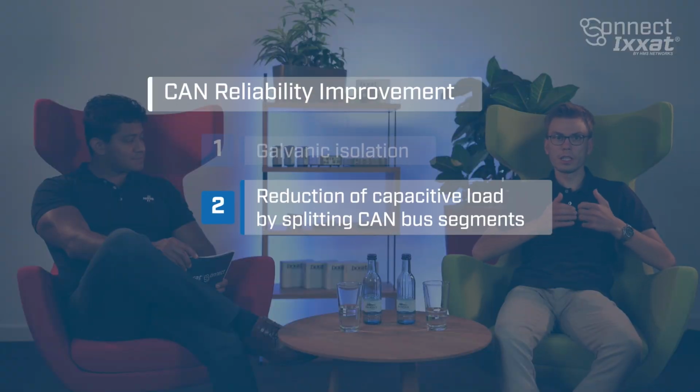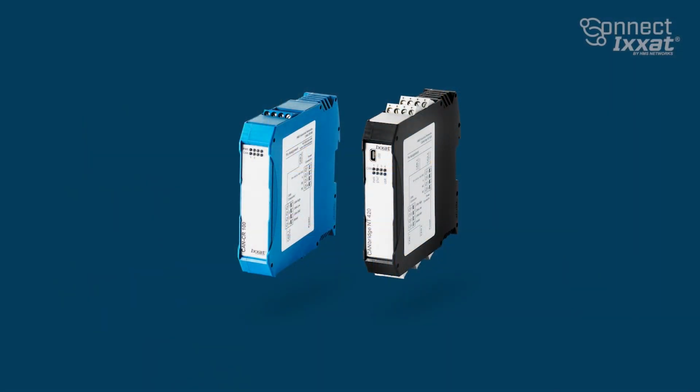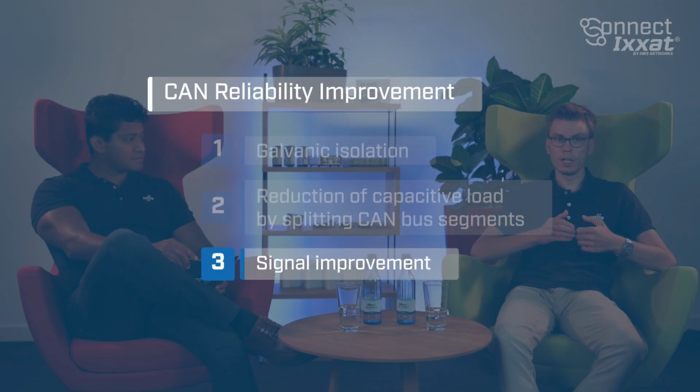And how about managing capacitive loads? When you have high capacitive loads that can dampen the signal edges and degrade the signal quality, you can segment the network using CAN bridges or repeaters, like those from Ixxat. This segmentation not only manages the capacitive load, but also improves the overall signal quality across the network. Another effective method is to reduce overall capacitance by splitting it into several segments.